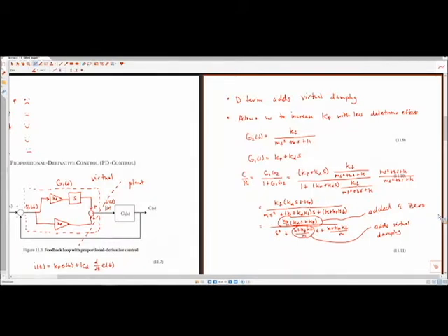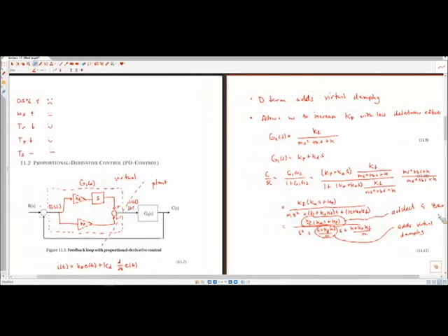Okay, so the reason for that is because we are using negative feedback. Right, so if we look at the error signal, error signal is R minus C. So if that's a positive number, that means that the reference is farther away, basically a larger number than our actual measurement. So we want to put more input into the system, right? And so by putting a negative gain, it's actually going the opposite direction. Right? So you can have negative gains. That's perfectly allowable. It's not usually a wise design choice.